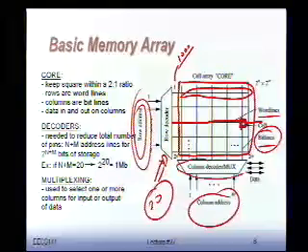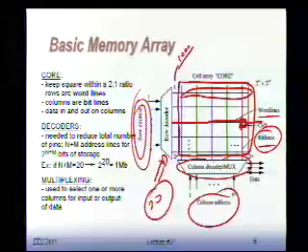That's where the column decoder then comes in. The column decoder can be considered as a multiplexer. I have 1000 bits in, I have 10 bits of control signals, and I want to pick one bit out of there. It's a giant multiplexer that selects one bit out of 1000, approximately. Okay? So that's kind of the structure of any memory you can talk about.